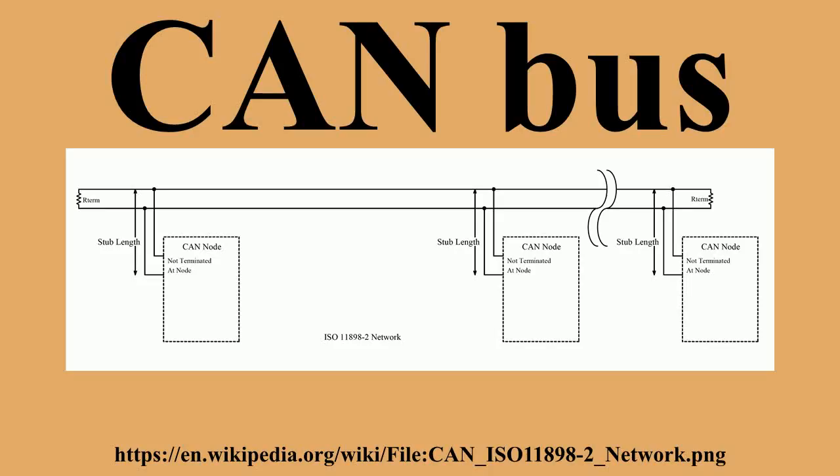A message frame consists primarily of the ID, which represents the priority of the message, and up to 8 data bytes. A CRC, acknowledge slot and other overhead are also part of the message. The improved CAN-FD extends the length of the data section to up to 64 bytes per frame.